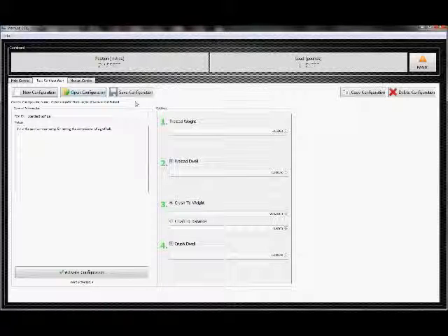I'm now going to go back to standard golf ball, and I'm going to activate the configuration, and that places it into memory in the program. It puts it into the control system, and those are the parameters that are going to run. So in this case, I'm going to have a preload weight of half a pound. Now notice here everything is negative. This is compression, which load cells treat as negative. So we have you enter the data in as negative. You can't enter in a positive number. You can't see me typing, but I'm actually trying to do so, and it won't let me. You must start out with a negative number.